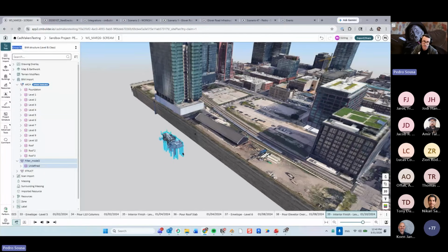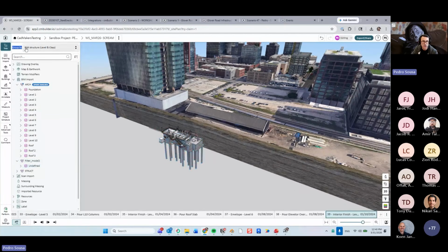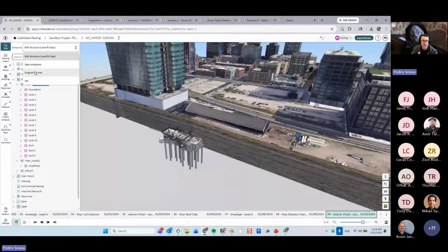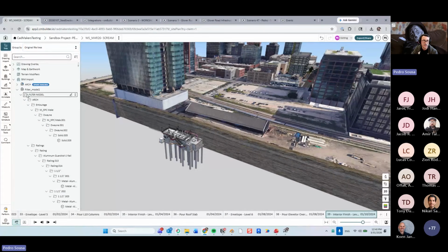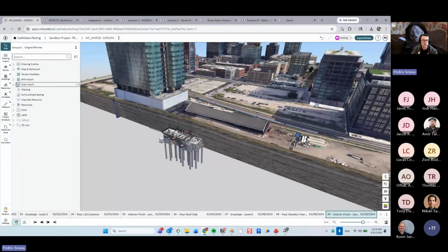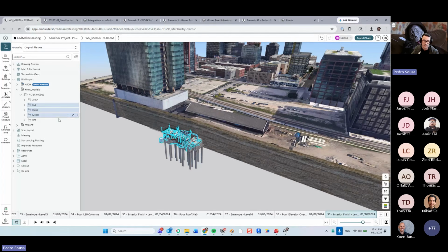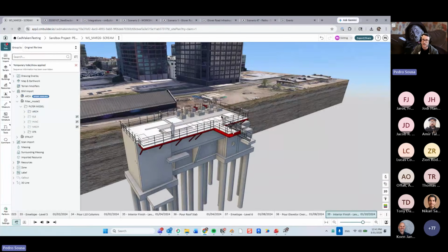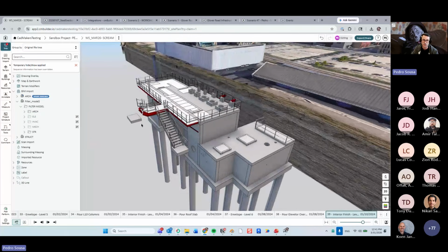So for Navisworks and FBX models, I will always suggest that you use a different grouping method for your tree structure. Go into the group by over here and change to original file tree. This will give you the same structure that you're going to find in the Navisworks counterpart. So if you open this model in Navisworks, you will see exactly the same tree structure that you have over here in this grouping method, the original file tree, right? So this way you can select a bunch of things that you don't want from that model and just remove them all together, right? If I hide these objects over here, you see that I'll have a way cleaner view of this model to work with, right?